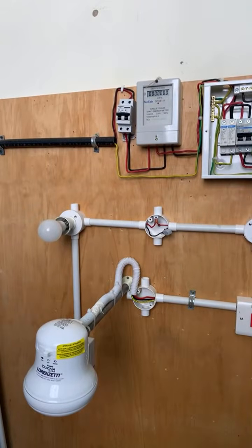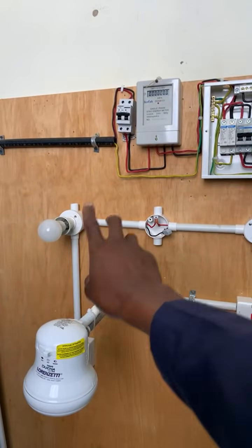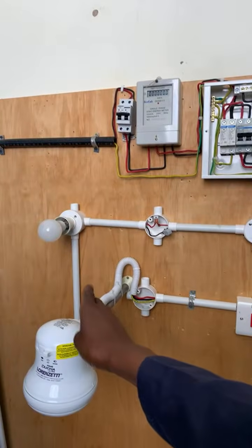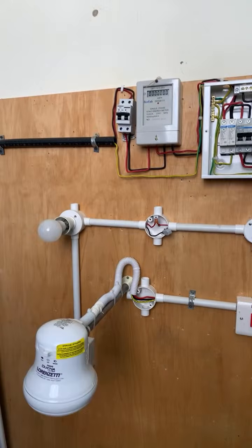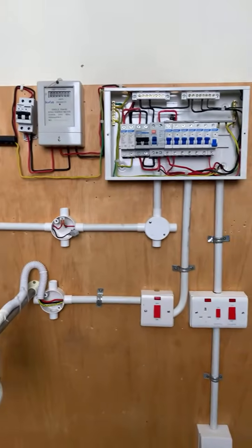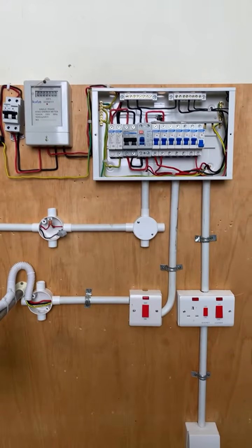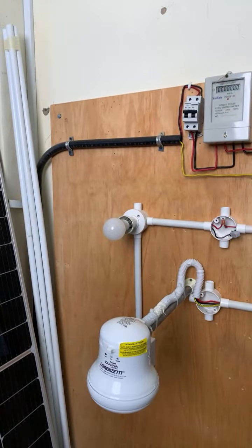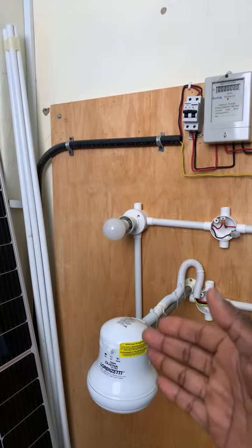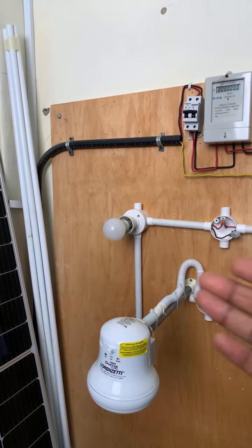Where do you start? Do you start by replacing the bulb? Do you start by going to the switches? The customer is clueless. As an electrical technician, you understand that probably there are a lot of issues in that home. Now, you definitely may go to the consumer unit, but one thing can stop you. If that lighting is serving several areas, I mean that MCB is serving several areas.